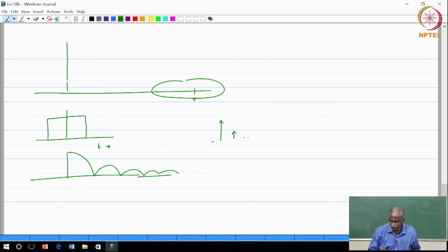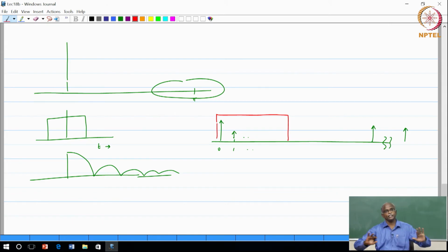I am just going to quickly sketch these things. So, 0, 1, some large number, and the signal is continuing. What we said was, I am going to take the DFT of this portion. It is effectively like setting all the other terms to 0, while these terms are taken without any modification. So basically a rectangular window was applied to this data.